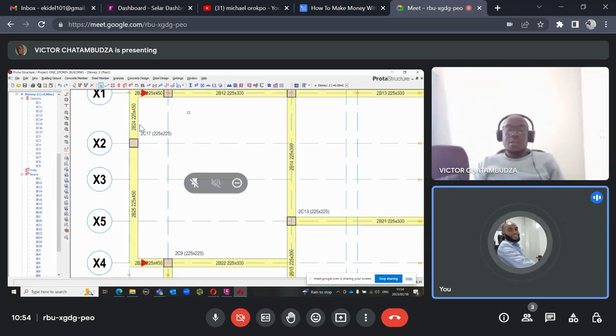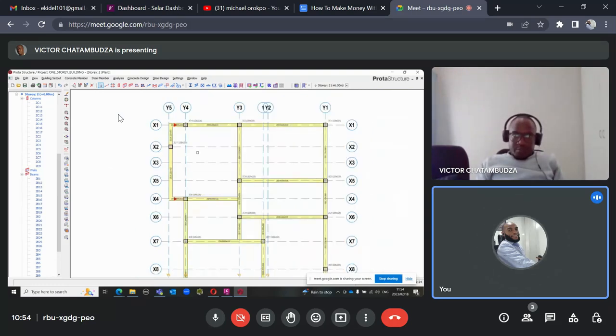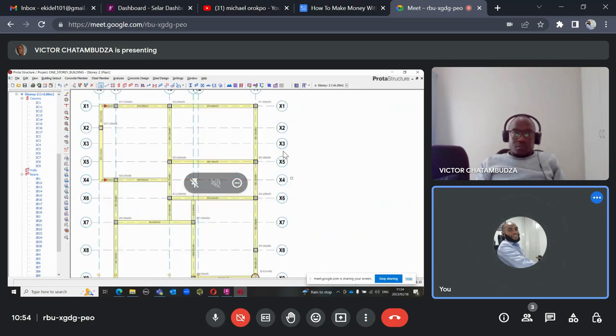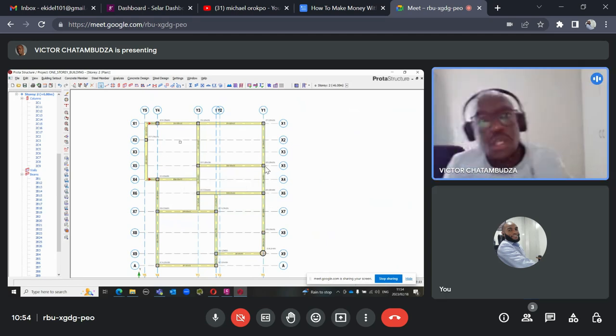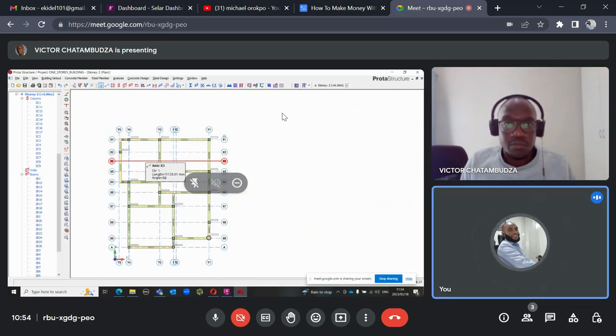Now with the same idea, just model the staircase area cantilever on the other side. So first of all, go and offset the grid on the ground floor to that face of the cantilever. So go to story one first.